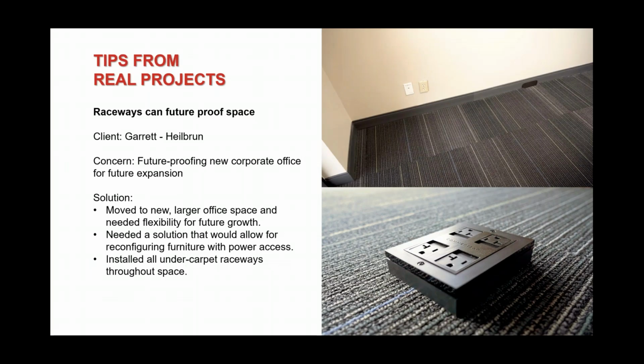So Steve, I guess I'll start with the specification stage. You did go into how to specify raceways and talked about the space use and if ADA compliance is an issue and, of course, aesthetics and function. I did want to ask you a specific question about over-carpet or over-floor raceways versus the under-carpet raceway option. Is there any consideration if you want to go over floor or under floor? Does it matter what type of flooring you're working with?